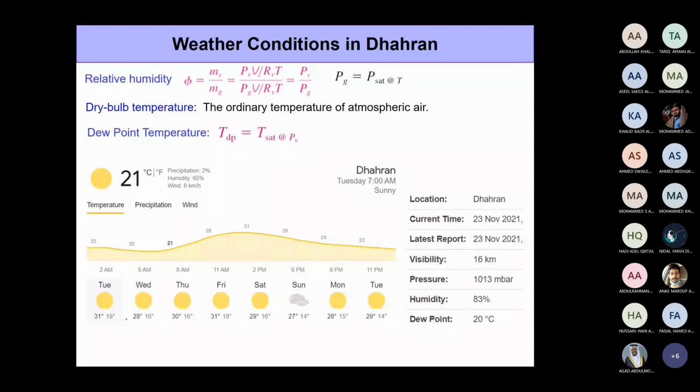So we have been talking about a lot of these temperatures. So I just wanted to give you an idea about what sort of temperatures we have around us. So this is the weather forecast for today. Now it's probably around 29 degrees Celsius. So 29 degrees Celsius is basically the dry bulb temperature. Okay, this is the normal temperature of the air around us. Now in the morning when I picked up these numbers, the humidity was given as 65%. So this 65% is nothing but the relative humidity, right? And the temperature was sort of low. So for the same amount of moisture level, the humidity you could say was slightly on the higher side.